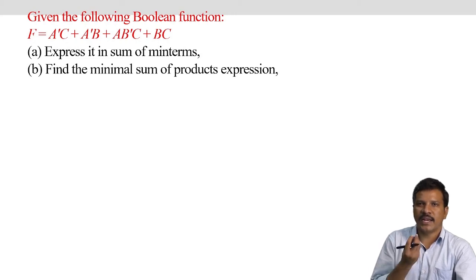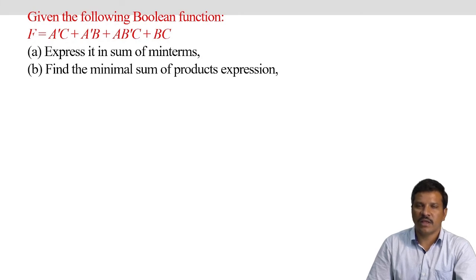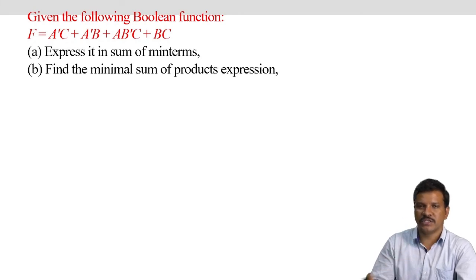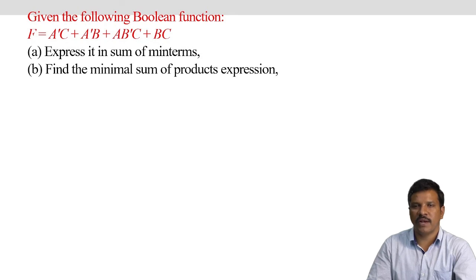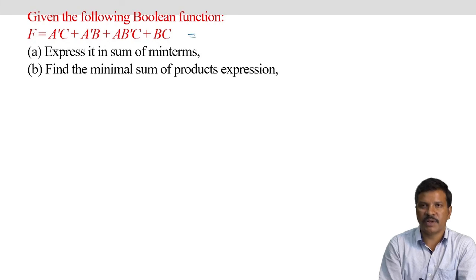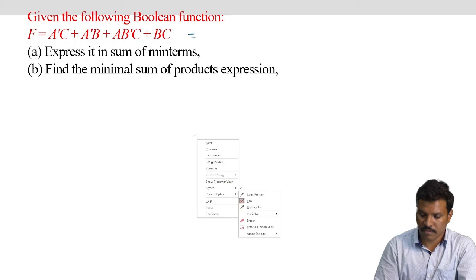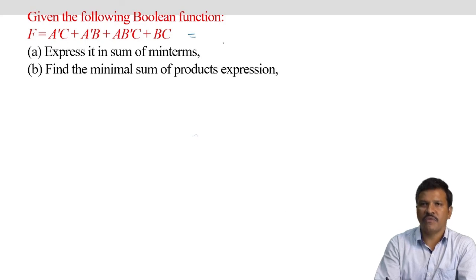So in order to get the minterm numbers, we can have a canonical form representation. Otherwise, we can also directly place those canonical form minterms in the K-map. One way is to replace this expression. This expression can be represented in canonical form.